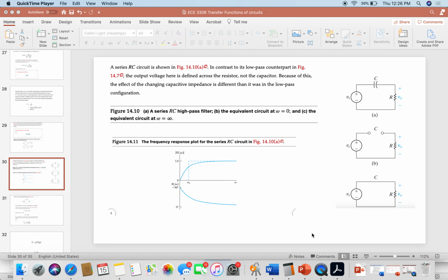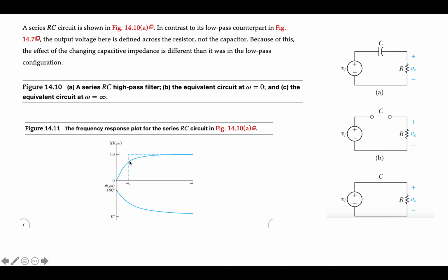In this video, we want to discuss high-pass filters, which, as you know, are filters that pass voltages from input to output at high frequencies. We're going to start by looking at the series RC. Once again, we are still discussing passive filters, meaning you have only passive elements: R's, L's, and C's. And we're discussing first order filters, meaning your transfer function will have a single pole, and that's known as first order behavior. The pole will, once again, be equal to negative the cutoff frequency.